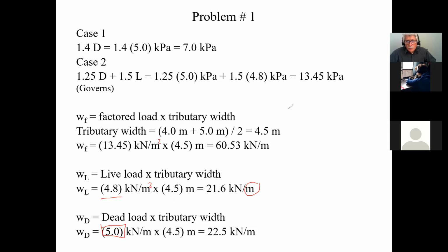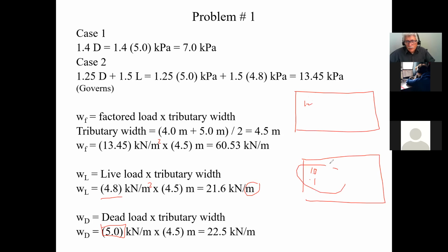And if you remember, when we looked at the load combination factors, you had all the ones for strength up here where it was 1.25 and everything. And then when we looked at the load combinations for serviceability, all the forces were multiplied by 1.0, 1.0. That means you use whatever specified loads to do your serviceability. You do not factor the loads.